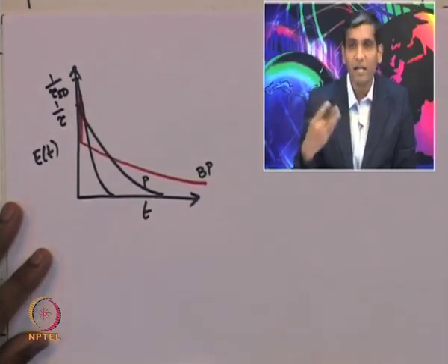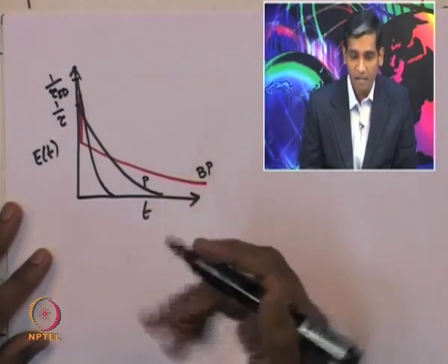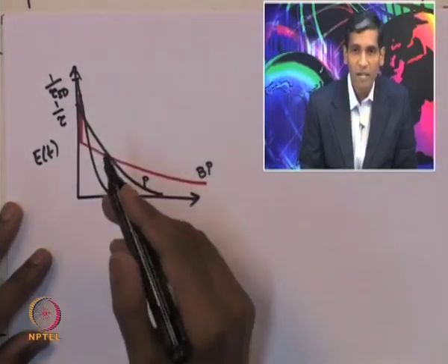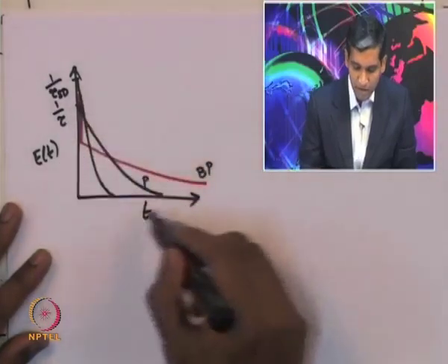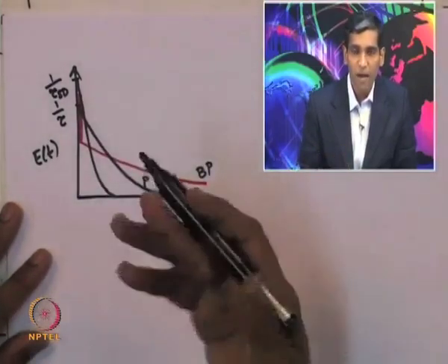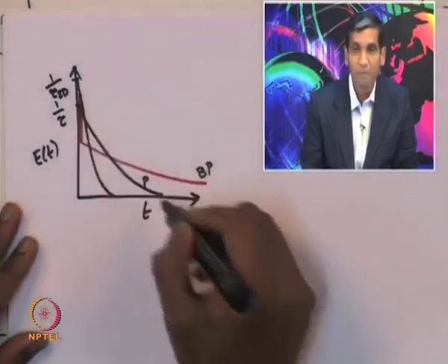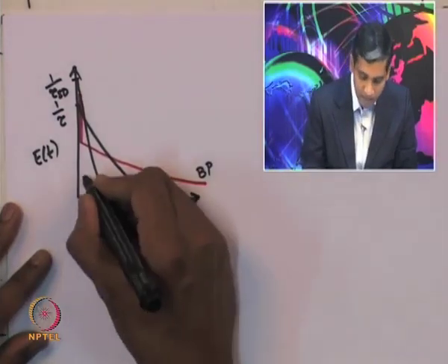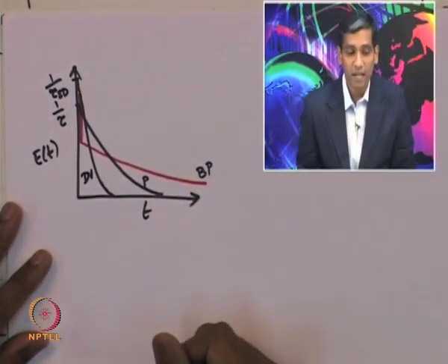So, now if there is real data for a tank reactor, then one can compare the actual RTD function measured experimentally with the RTD functions present in this graph, and that can provide a clue, compared with the perfect operation, whether there is a bypass or a dead volume present inside the reactor.